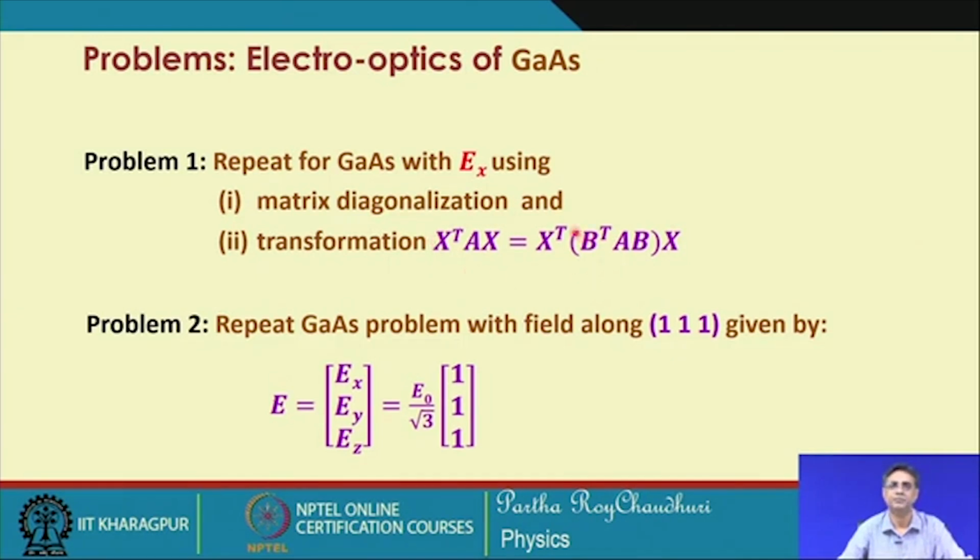That is the same protocol, same rule, that has to be followed for all modulators. From the birefringence we calculate the phase delay, and from the phase delay we calculate the half voltage, that is how much voltage is required to get a phase delay of pi, so that the modulator can be switched from state 1 to state 0 or state 0 to state 1.